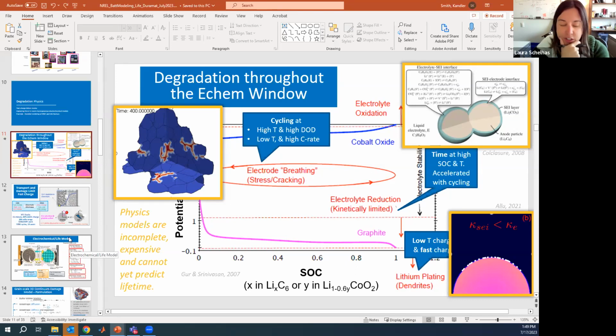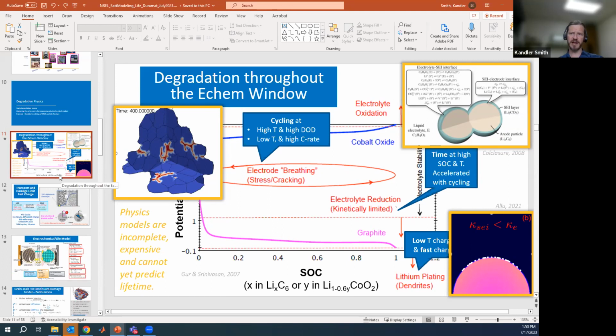And then just because I'm curious, when you talk about version 2 from a manufacturer, what type of changes are they making in their materials? Is it a slight chemistry difference? Is it a physical difference in the way the batteries are put together? What is that? Yeah, I'd say they probably somewhat routinely need to change suppliers or have a diversity of suppliers. So it might be that their LFP is coming from a different supplier, and so they need to validate that, and maybe lifetime changes somewhat for that.